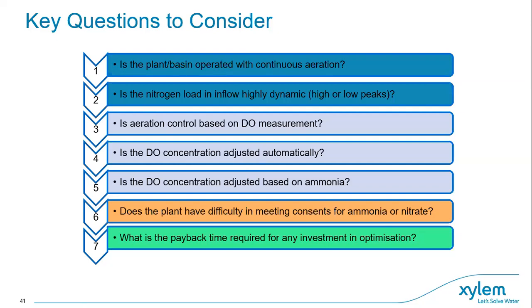In most cases, we still see very much a fixed DO set point and very little chance to optimize in that. So the capacity and drive to use things like ammonia control or variable DO control really does give a step above all the things that Magnus talked about earlier in terms of gaining small incremental and in some cases large incremental efficiency gains.